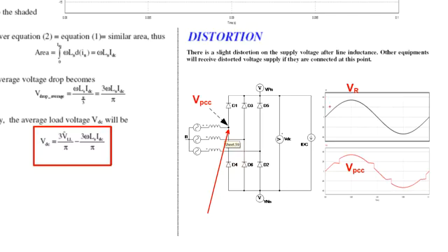This is the voltage from that point to the neutral point. Similar to the red phase voltage, here we have the voltage just before the source inductance. We have a nice sinusoidal voltage, but due to the rectifier, the voltage at the point of common coupling has been distorted.